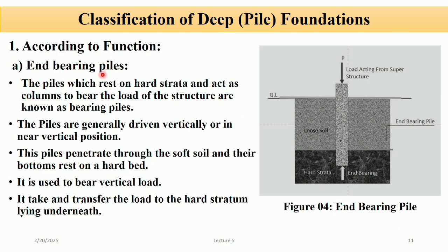End bearing pile. The pile which rests on hard strata and acts as a column to bear the load of the structure is known as an end bearing pile. An end bearing pile is a type of deep foundation that transfers the load of a structure directly to a strong, stable soil layer or rock beneath weak soil. The pile is driven or bored into the ground until it rests on a solid layer.